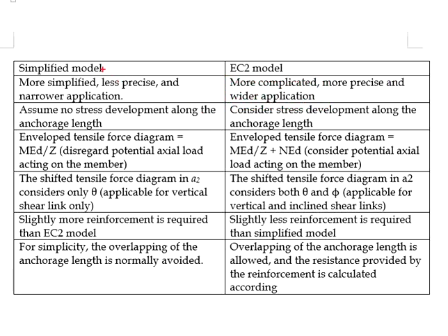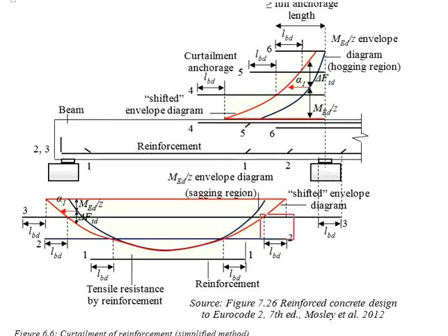The main reason behind this precision is the assumption made on the anchorage length. The simplified model assumes no stress development along the anchorage length, as seen here.